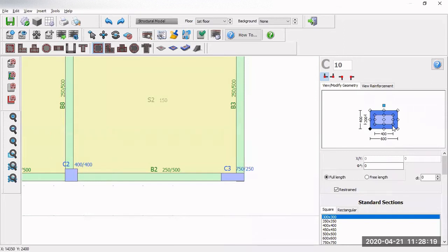All right. So in this example here, what I'm going to do is I'm going to do a jacketed concrete of 100 mm, the whole perimeter of this column. All right. In this column here is 250 by 750. So I change this dimension, maybe 200. Maybe I change it become 950. All right. And then the original one is the original column for C3 is 750. Okay. And the width in this case here, the original is 250. So I strengthening 100 mm for both sides. So it's become 240. And the original column size is 250. All right. So this is the strengthening